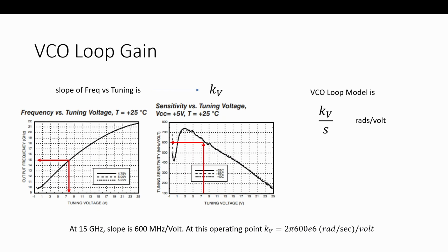And what you're also seeing is the slope isn't completely linear, right? So depending where we operate, that slope is going to change. That's important to notice because you're going to see how that slope drives the loop bandwidth. That means we're going to have different loop bandwidths depending where we operate, different stability, etc. And what I'll typically try to do in a loop, especially easy if it's a software loop, is to linearize the component right at its source. Because if we make that linear, then we're fixing it from cross dependencies of other changes later, right at the point and keeping it very linear.